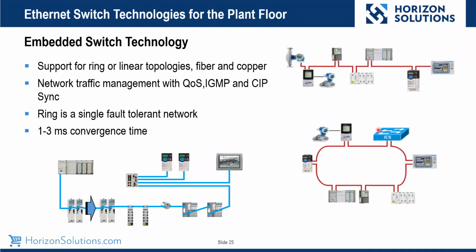If you notice, we have switches that sit on the device level ring, so you could branch off and go to other devices like HMIs. The topology I really like, especially for machine builders, is this hybrid topology, as I call it, where we have our high speed, time sensitive products all daisy chained together. So like this controller, this is our new, say, 5069 Compact Logix.